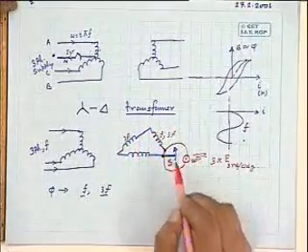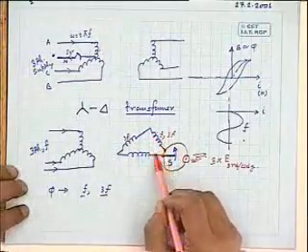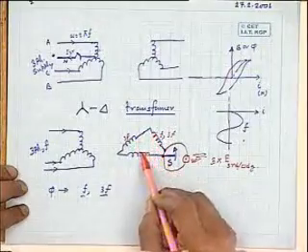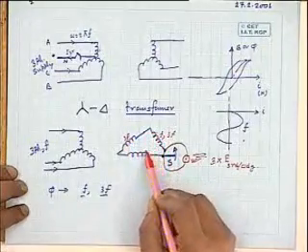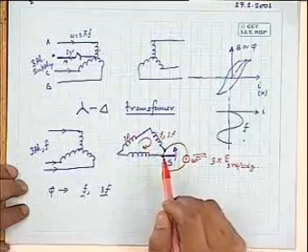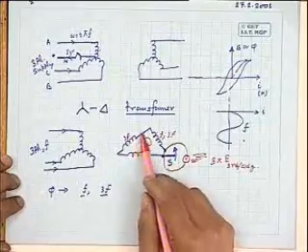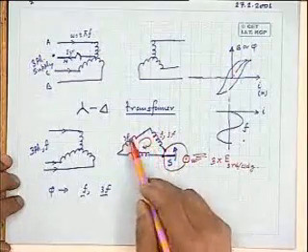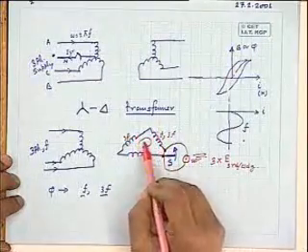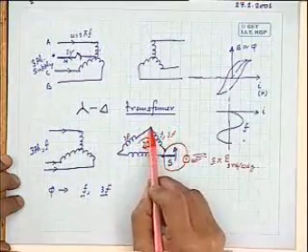Now, if this switch is closed, what is going to happen? This third harmonic voltage, which is induced here in the windings, each of the winding, will now circulate a current here. The magnitude of the current, of course, will be decided by the third harmonic impedance of these windings. But some third harmonic circulating current will flow.